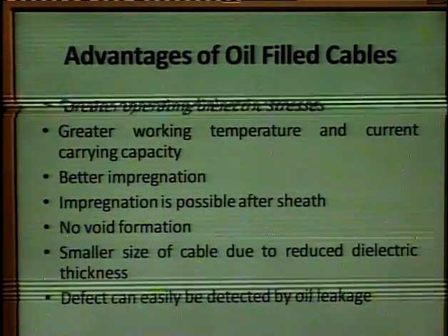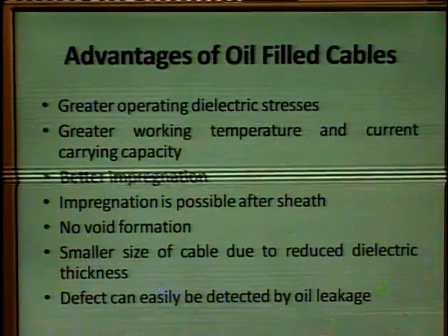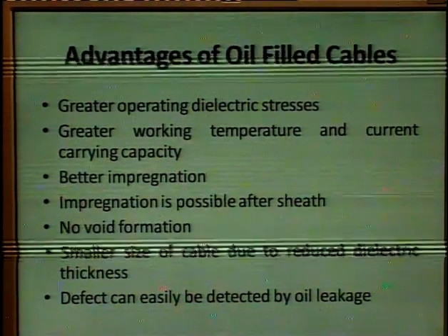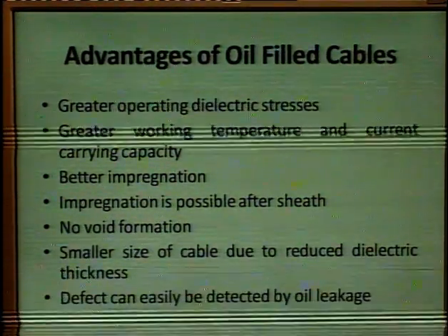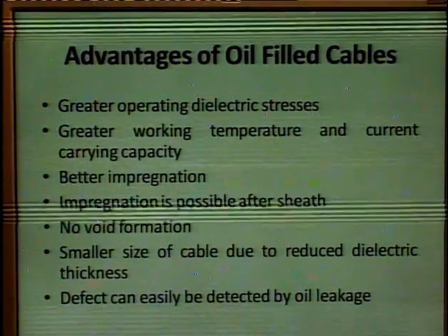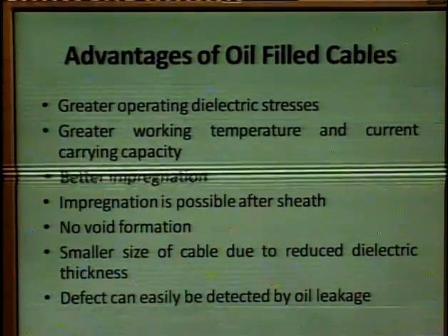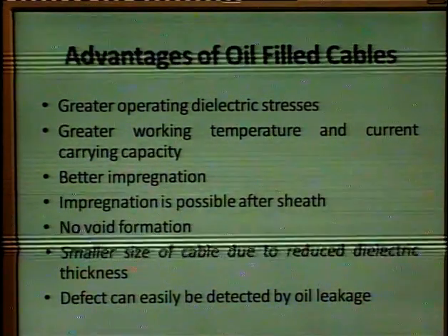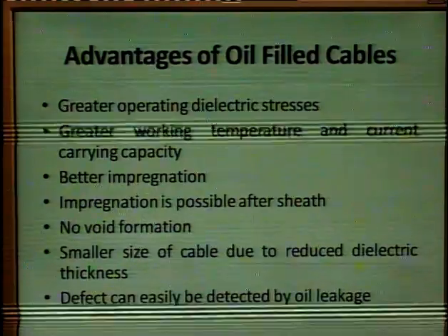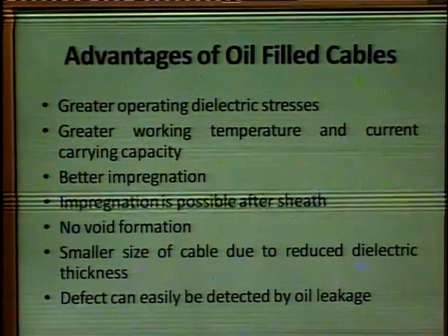Then we have some advantages of these oil filled cables. First is the greater operating dielectric stresses. Then the greater working temperature and current carrying capacity.